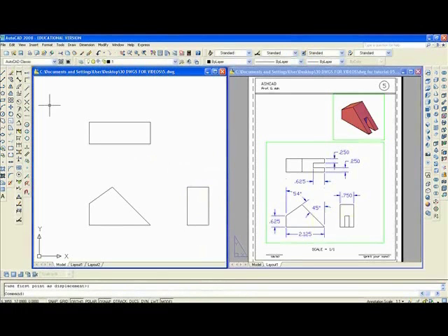And we have to also draw a line from here up. Sometimes it helps to work on all three views at the same time. Enter. I want to offset. O, enter. 0.625, enter. This line. Enter twice to offset. 0.25. This line here, this line here.